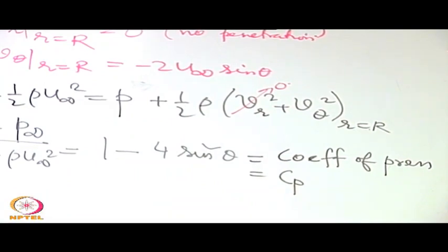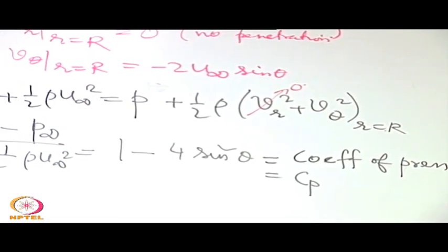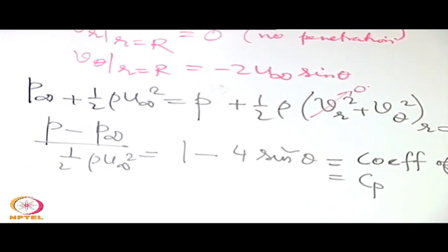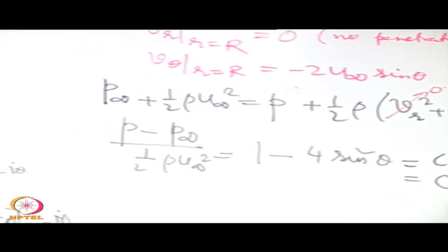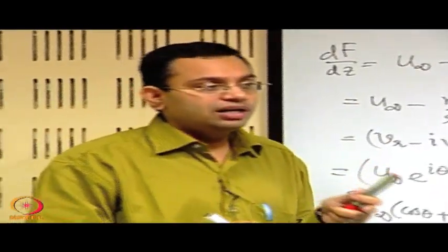So that means, see, we have got a pressure distribution and we may use it even for a boundary layer theory till there is boundary layer separation, because whatever is the pressure imposed by the free stream from outside the boundary layer, which is like a potential flow, same pressure is acting within the boundary layer.